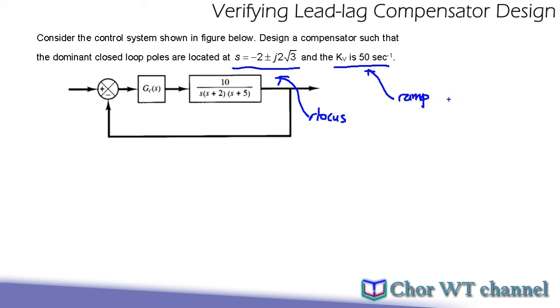However, Matlab does not have a built-in ramp response function, and hence we'll be using the step response with a minor tweak to generate the ramp response so that the steady state error can be captured to verify the steady state error requirement.